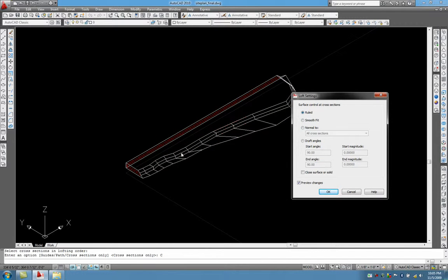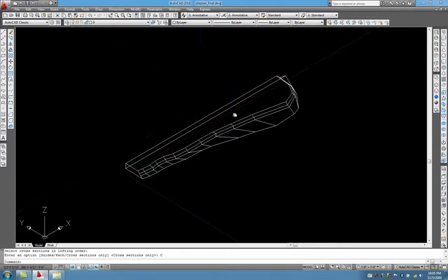And here's an example of what you'll get. No need to close it since we've already capped off all the edges. But if we hadn't done that, what it would have done is it would have made a solid by connecting this top line to the bottom of the other one. So there would have been instances where the back side of this topo would have gone through the front. So that's why we close it off on the back, to prevent that anomaly. So you hit OK, and then all the other lines go away.